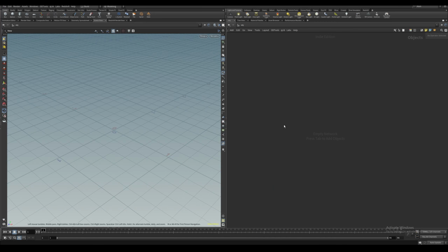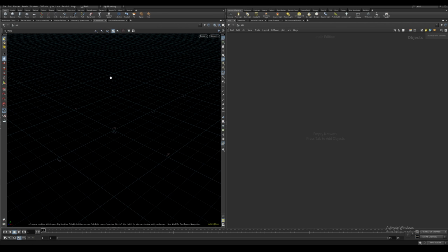I'm going to start off by doing a smoke simulation, which will be used to drive our particles. So first I want to come in our viewport and change the background color to dark. And I also changed this frame range to 96 from 240. For the smoke source, I'm going to use a sphere.